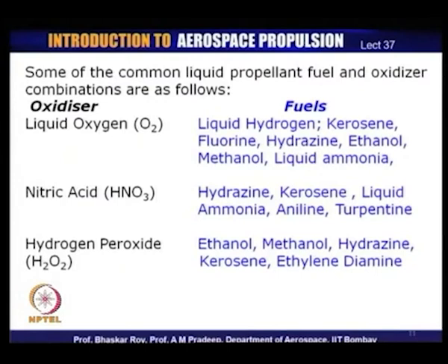The other possibilities are, if you use nitric acid as oxidizer, you can have hydrazine, you can also have kerosene, and you can have liquid ammonia, aniline and turpentine. If hydrogen peroxide is the oxidizer, you can use ethanol, methanol, hydrazine, kerosene and ethylene diamine. Now, you see there are a number of combinations that are possible, and as I mentioned, some